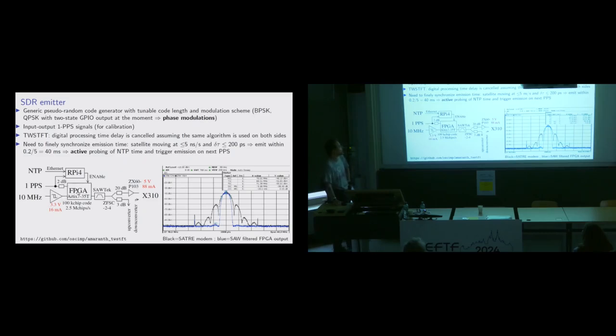You've got 1 PPS that triggers the generation of a totally random sequence. Everything, so carrier, BPSK, are all generated in the FPGA, and actually there's a payload on top of this that we're not going to care about. And whenever you're doing SDR transmission, you know that you've got a lot of unwanted parasitic spectral components. So, surface acoustic wave bandpass filter, and a loopback path to measure